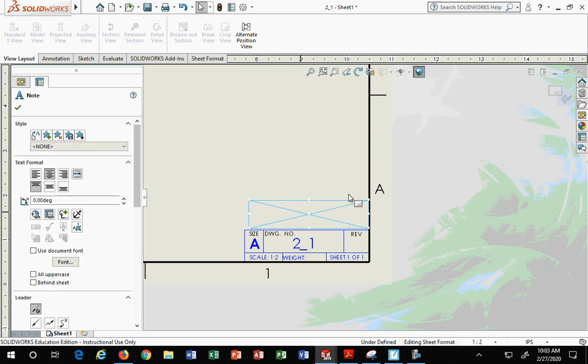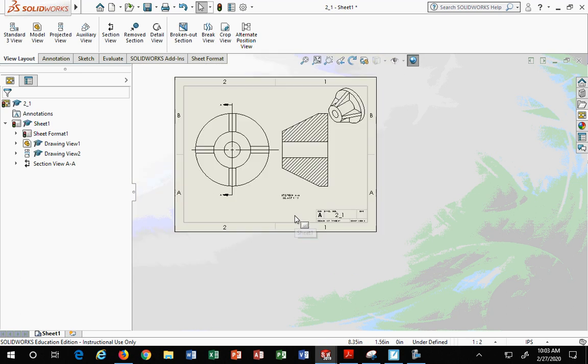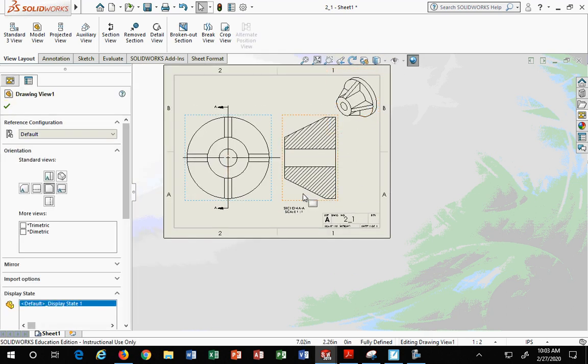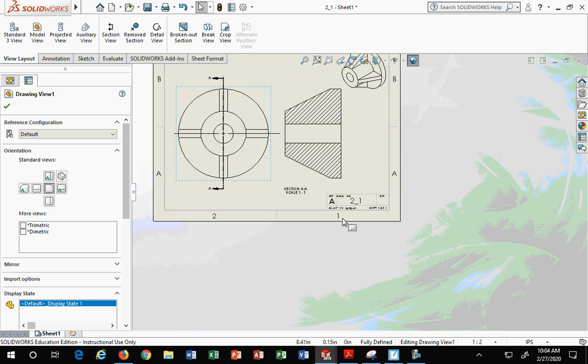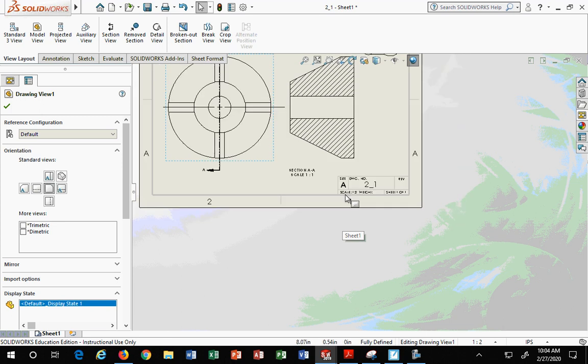It is subjective what I just did, because I'm not going to worry about having a title in the drawing. If you must have a title in your drawing, then I recommend you change the scale of your model. I'd rather keep the scale 1:1 and change the title block. That's what I just did. Because what's the scale of the drawing? Yes, you're correct.